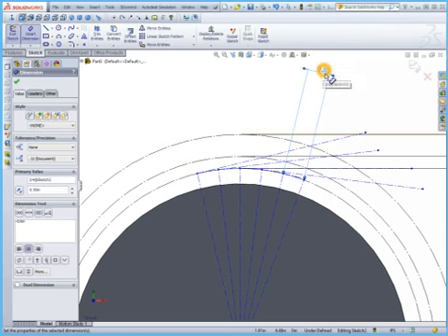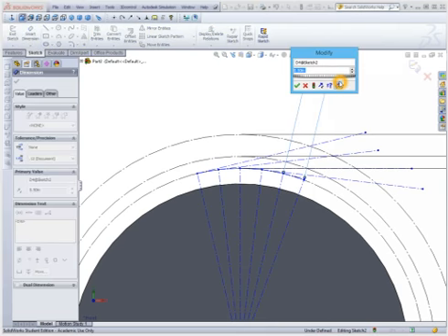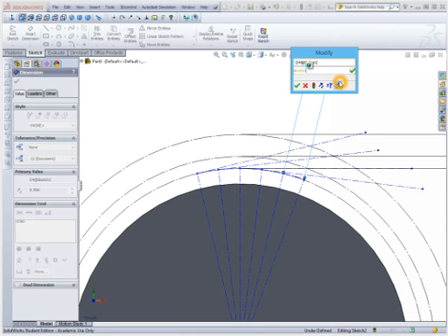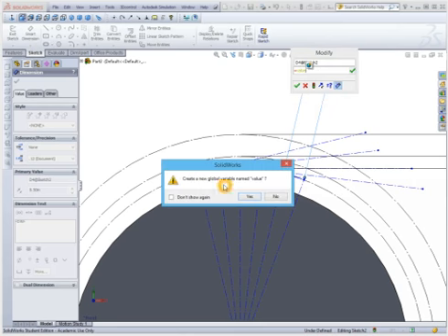And so I want to make the next line twice that without saying that it's exactly 1 inch. I want to set it as an equation. Well, the way I can do that is actually click on my original dimension, and I can set this as a global variable. It's going to maintain its length for now, but I'm going to say it's equal to some value. So we'll just type in value as a variable. This text does not matter, but it's going to save that consistently. So here it's asking me if I want to create a new global variable named value. Yes, I want to do that.